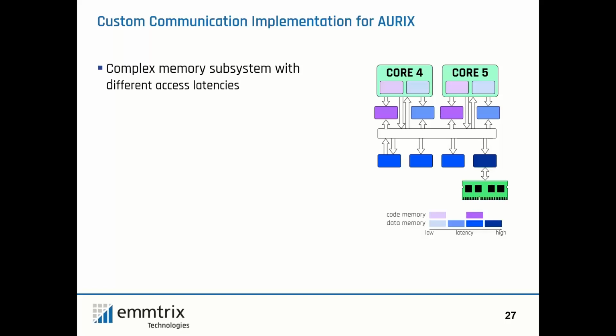For this application, because of the complex memory infrastructure of the AURIX, we did a custom communication implementation, and so we had to decide where to actually place the buffers. Placement of shared data structures is critical for performance in a system that has so many options to place code and data with different access latencies.